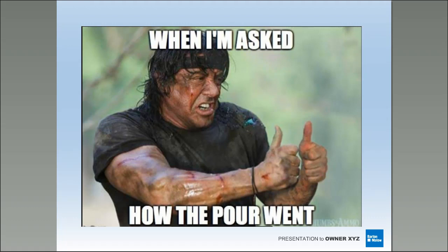Jill, consider using concrete sensors in the plastic concrete to accurately determine concrete strength, to provide the polishing contractor an accurate strength per slab. Yeah, we've used sensors in a lot of our slabs to monitor the strength, the maturity of it, and everything else. That's a great point, Jill. Sensors are becoming more and more prevalent in the industry, for more than just mass concrete.